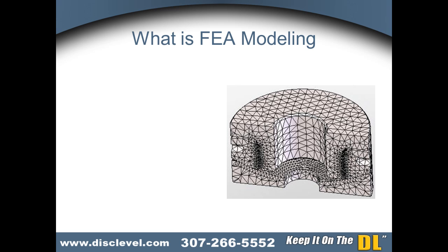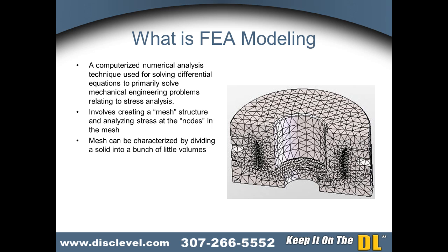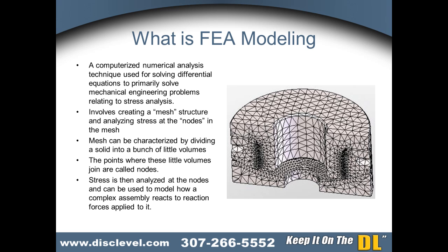What is FEA modeling? It is a computerized numerical analysis technique used for solving differential equations to primarily solve mechanical engineering problems relating to stress analysis. It involves creating a mesh structure and analyzing stress at the nodes in the mesh. This mesh can be characterized by dividing a solid into a bunch of little volumes. The points where these little volumes join are called nodes. Stress is then analyzed at the nodes and can be used to model how a complex assembly reacts to reaction forces applied to it. It verifies calculations to predict failure.